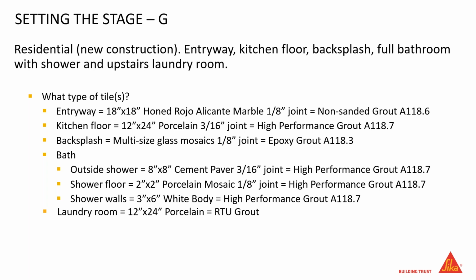Has a little bit of flexibility to it, but it is stain resistant, does not need to be sealed, easy to clean up, and it's really a hard grout to mess up. We could use that ready to use grout in some of these other applications, but we're putting it in the laundry room on the laundry floor.